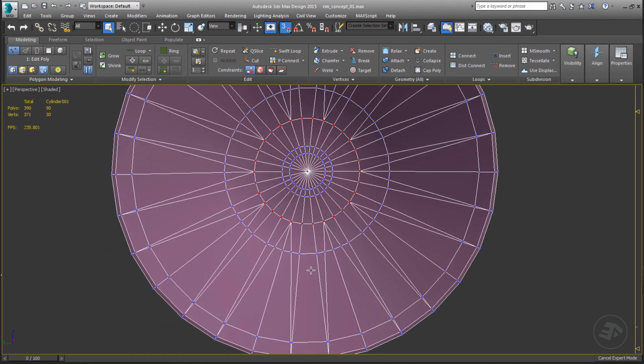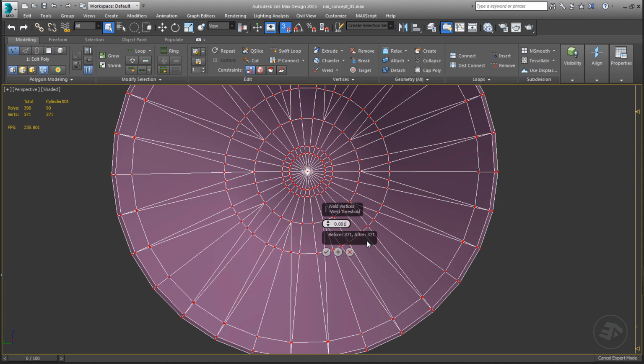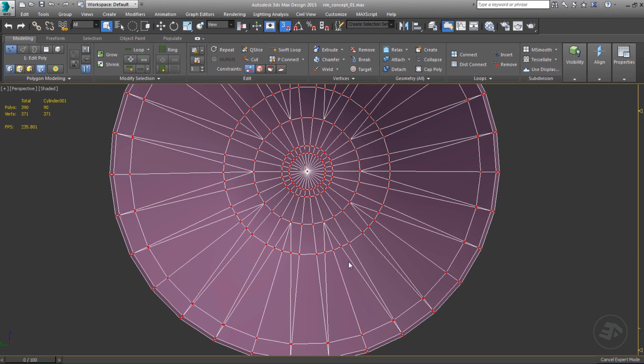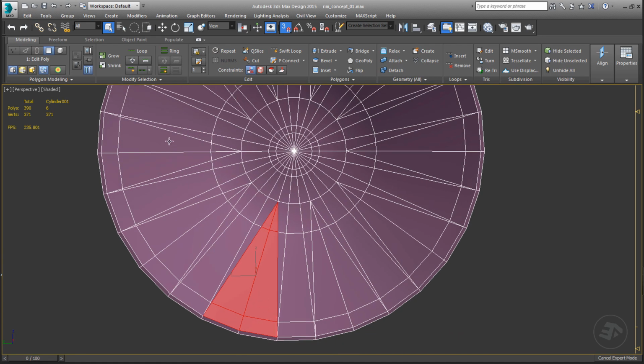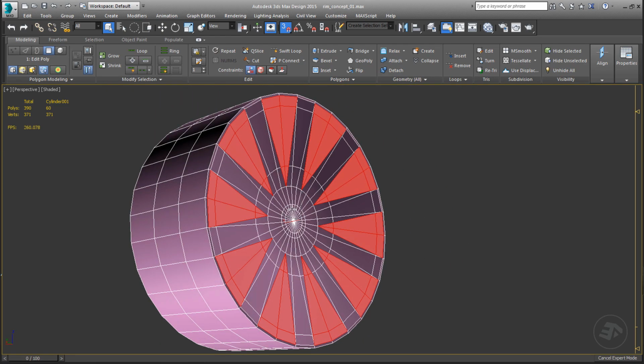After using the Cut tool, you should check for isolated or overlapped vertices. At this point, overlapped vertices are not required. Use the Weld tool to weld any overlapped vertices. I am using 1 mm as the check distance, and our design is clean. One more thing for this designing technique: we need to check for similar shapes to ensure we maintain the diagonal symmetry.